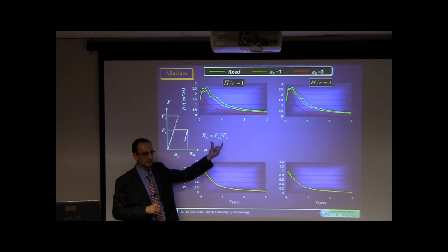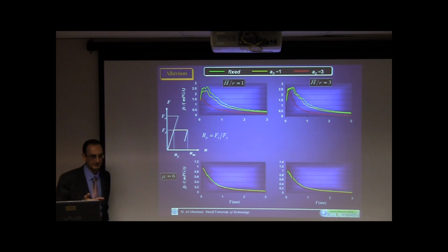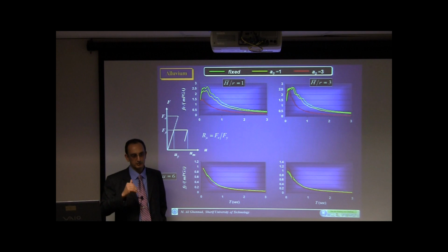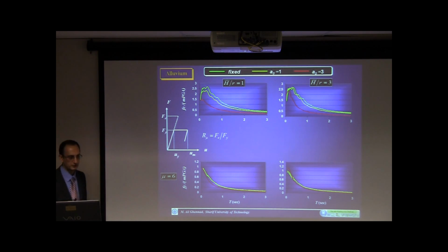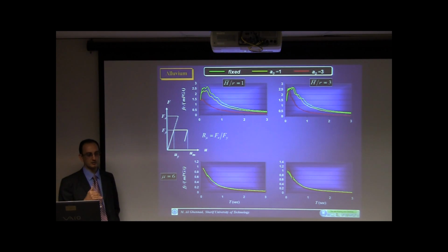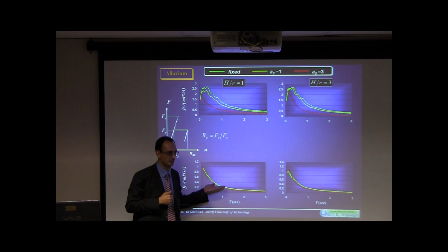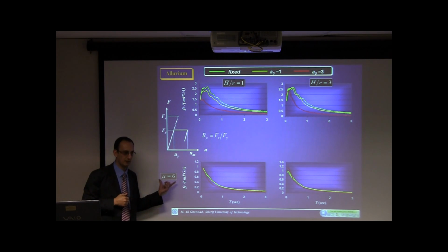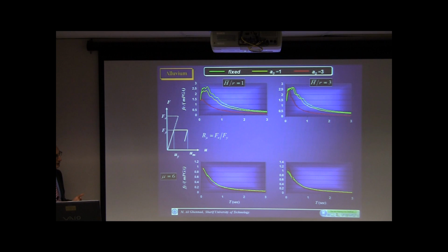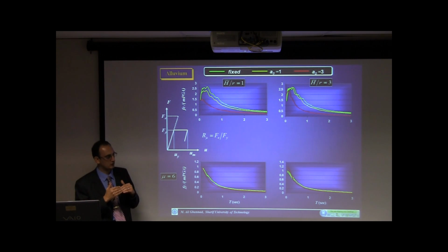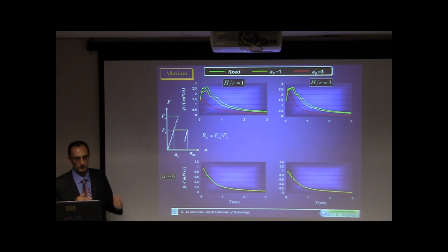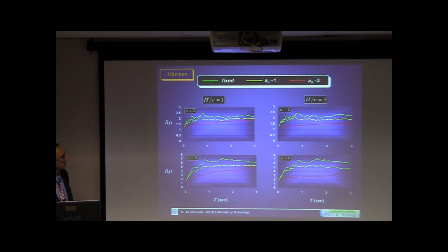And this is what is implicitly behind the regulations in ATC 3-06 and NEHRP 2003 that reduce the demands much less than really needed to maintain this level of ductility. So using this reduced base shear, one can expect much higher ductility demands in the structure as a part of the soil structure system.